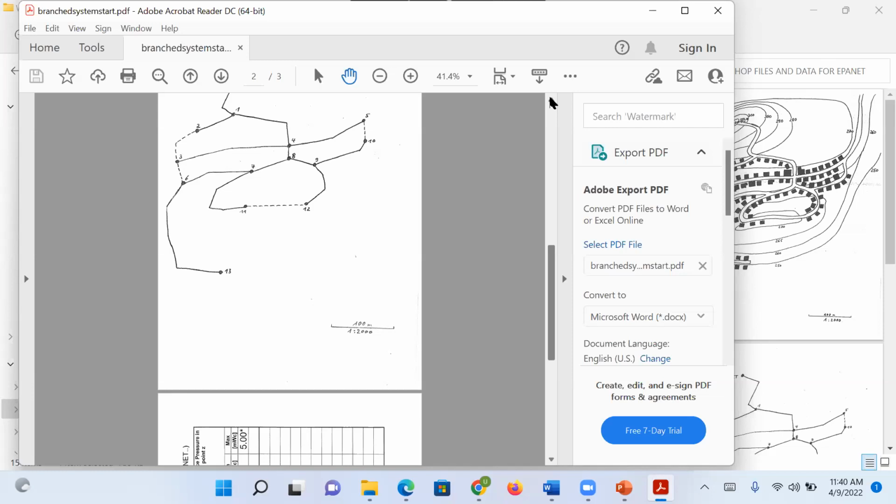You have to project, sir. On the first day, we say that you project your population for 25, 30, 40 years, depending on what your client wants. In fact, you can project for 50 years. In the Nigerian case, if you are doing a water recirculation system, project for 50 years. So for those empty plots, there's no way you will tell me that in 50 years' time or in 20 years' time, properties will not come there.